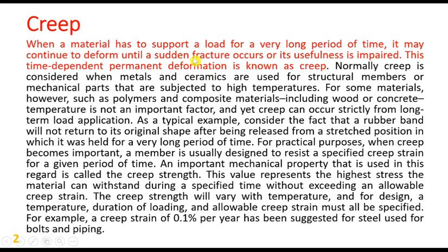Creep: when a material has to support a load for a very long period of time, it may continue to deform until a sudden fracture occurs or its usefulness is impaired. This time-dependent permanent deformation is known as creep. Normally, creep is considered when metals and ceramics are used for structural members or mechanical parts that are subjected to high temperature. Normally for high temperature, but not always.